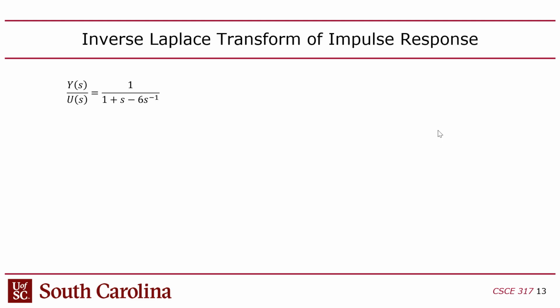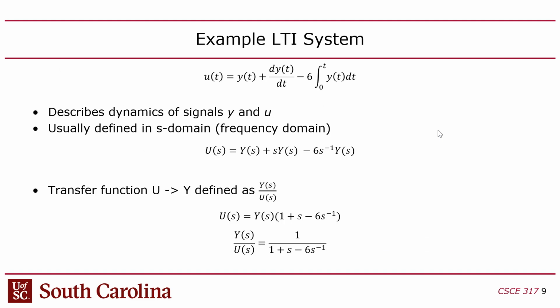All right, so what about the example that we looked at then? Yeah, this is the same example we looked at before. So this is a transfer function, and again, let me clarify this. When you're looking for poles, the poles are found for the transfer function. Obviously, those poles are going to change if I use U as the output and Y as the input, right?